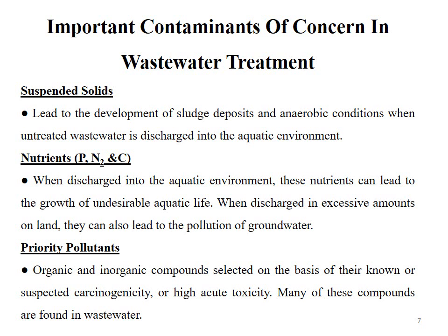These suspended solids are actually any material, any solid particle which remains suspended inside the water. These suspended solids lead to the development of sludge deposits and anaerobic conditions when untreated wastewater is discharged into the aquatic environment.